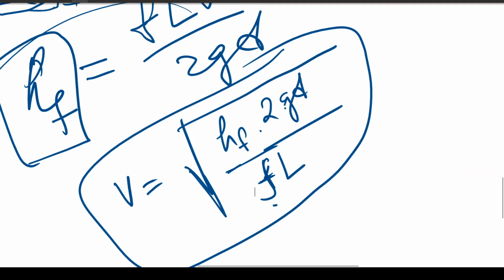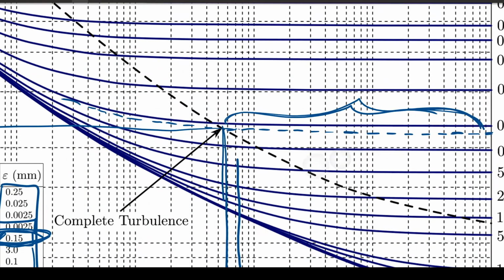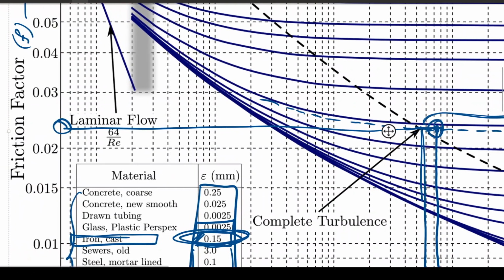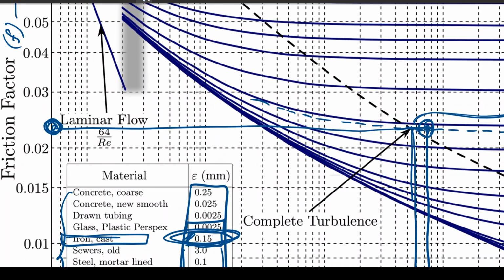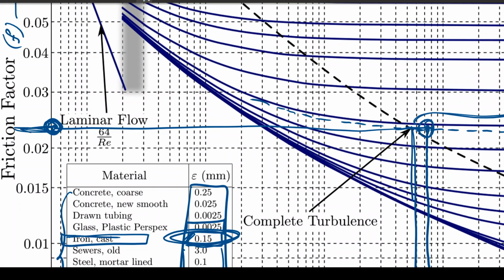let's look at the graph again. Where is that value? This is 10, 9, 8, 7. If we go up, it's actually 7.5, so it will be somewhere around here. If we go up here, then we'll hit the curve that we have drawn, this dotted line, somewhere around here, and corresponding to this, the friction factor is whatever we have assumed, because beyond this the friction factor doesn't vary much, it is almost constant at 0.022 here. Therefore our assumption was correct.